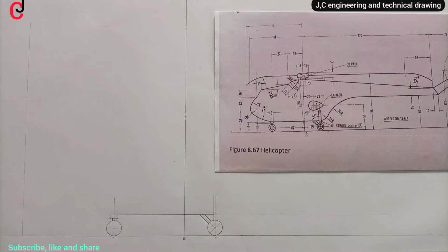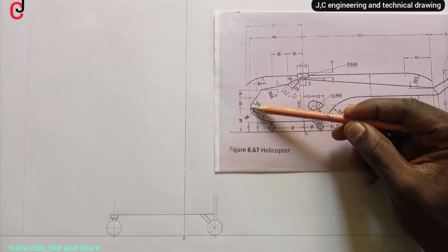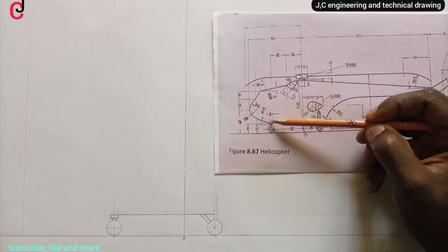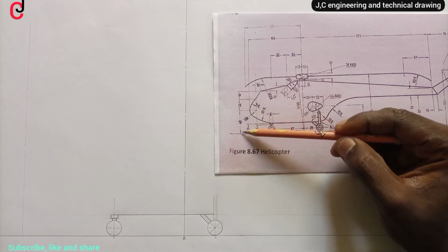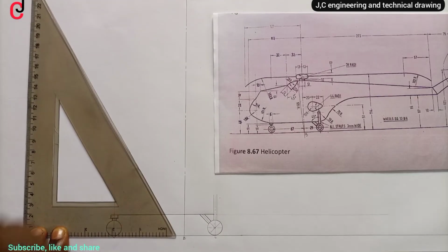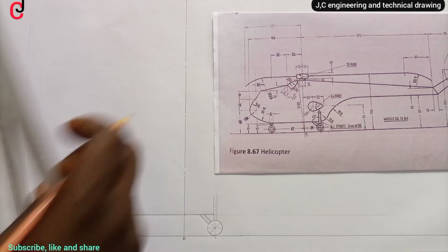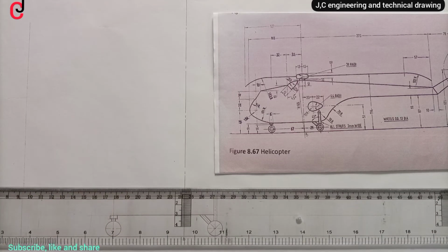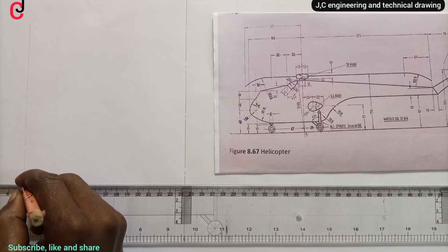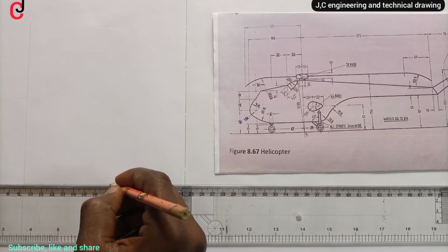And then from our diagram, so we should measure 48. We want to get this curve here so that we can join these together. So we should measure 48 mm upward from our vertical line. We take 48 mm, indicate with the point, and then we draw a light horizontal line